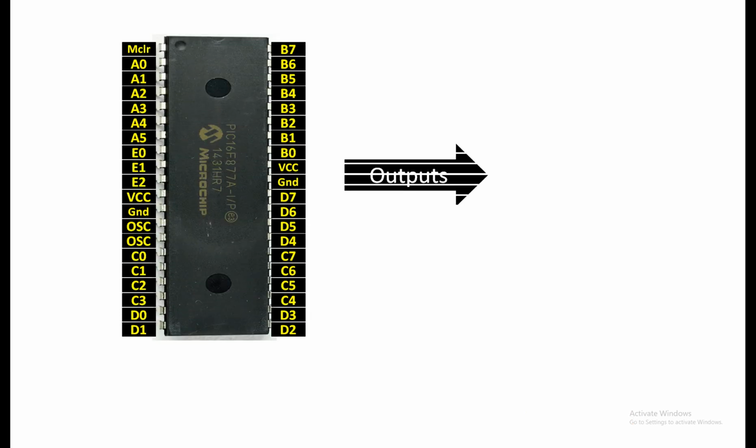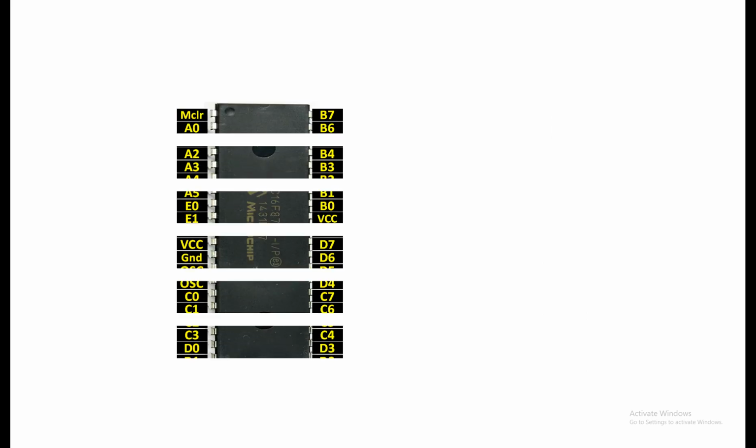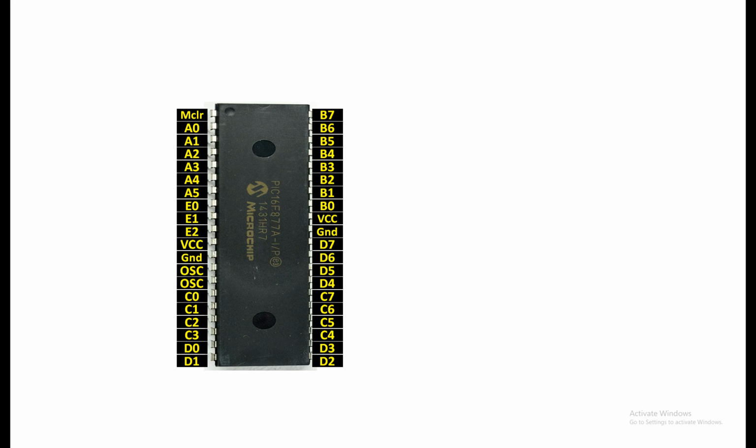Now guys, what we are going to do here is that we will use our PIC microcontroller and an LED. So let's connect them. So this is our PIC16F877A having 40 pins. It's a DIP version, and this is an LED having 2 pins, one longer, one shorter. You know, the longer is the power, shorter is always a ground. And we will need a safety resistor. It can be from 220 ohm up to 500 ohm. Higher the value, lower the brightness of the LED will go. I'm going to use a 220 ohm resistor because it works very good with the 5 mm crystal type LED.